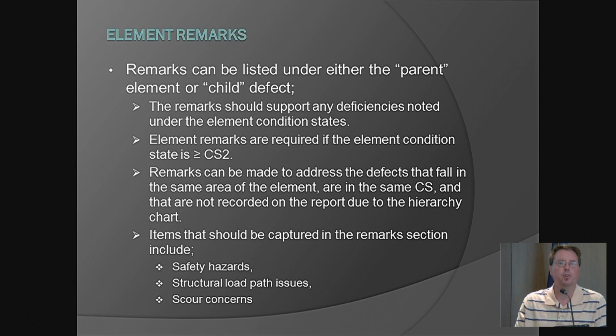It makes it easier, we found talking with other bridge owners, to be able to find those and where the defects are actually located if they put them under each of the specific defects instead of the parent elements. But going back to what we talked about before, say if you have multiple defects in that one section, then they can use the parent element comments and remark sections to capture all those additional things that might be wrong with that particular element.